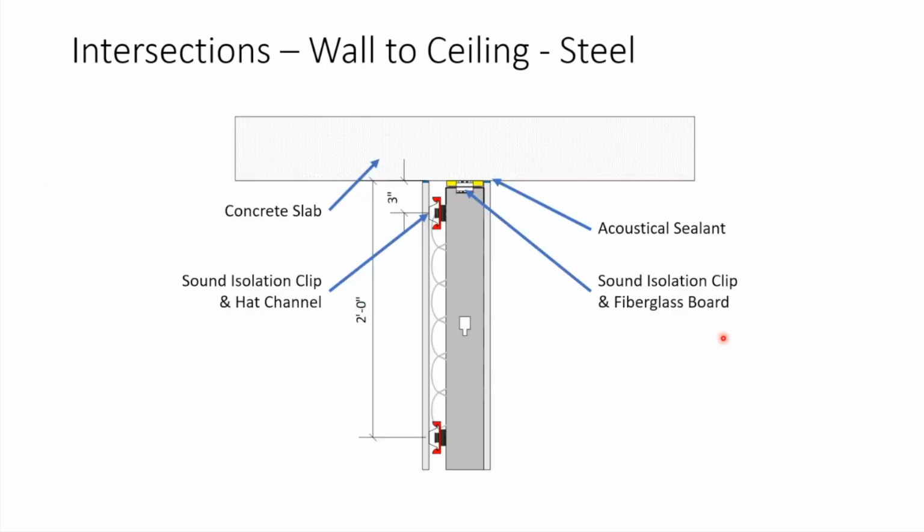Steel frame construction, I don't have in here because it's a lot trickier. Where you've got a steel stud wall and steel joists, that also tends to be a lot less common. More commonly, you have steel studs to a concrete slab or concrete on a metal deck or something like that. So here again, we may want to reduce the amount of sound transmission from the space above down to this. And so we can have some acoustic isolation. We have seals here, and also we've got this gap here, so we put some insulation in that as well to kind of protect this cavity path through here.